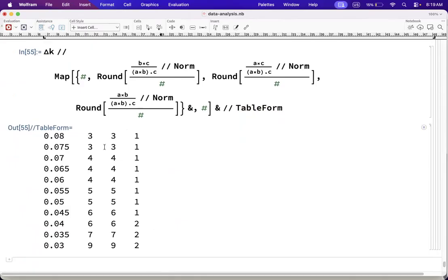So for delta K, 0.035 is the convergence that we already computed previously, in the beginning, when we computed the bulk of silicon. It means that to do it at the same level of convergence, we have to use this 772. But in this case, since we don't want interaction between these two slabs, we are going to replace the 2 by 1, because the slab is a surface along 3, and we don't want to take into account any interaction in the Z direction.